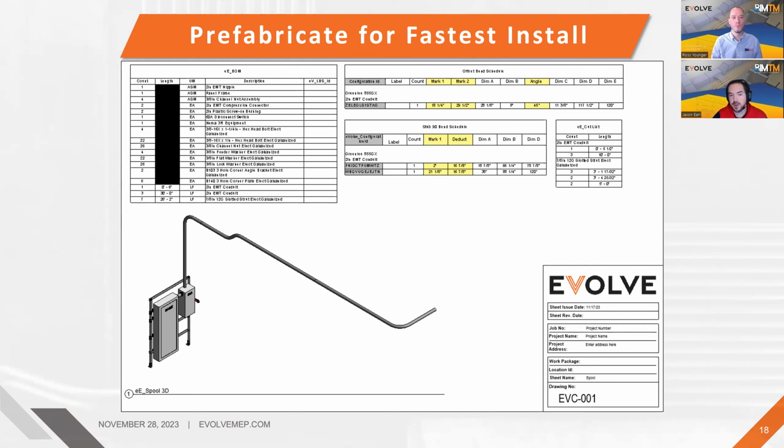So with electrical conduit, bending is definitely an issue from the model. Our bends have all of the marks and dimensions needed to make those bends without making any dimensions in the drawing. So this is just an example of a prefabrication spool drawing that, if you're working in an existing space, you could take advantage of 3D scanning and go and prefabricate that work.